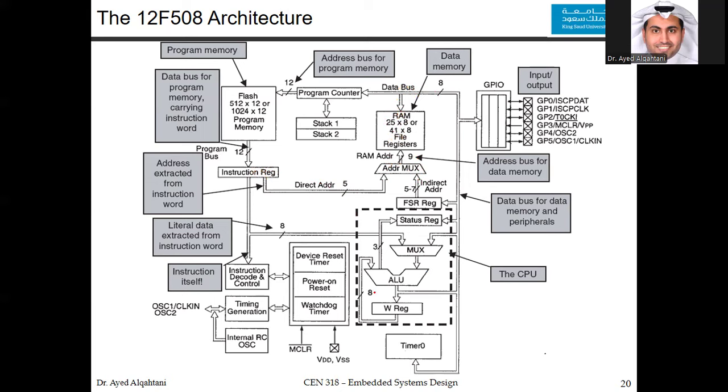And you can see here we have the CPU or the ALU, where you have either an immediate value or the variables that you get from the memory right here. And you have a multiplexer to choose which one you want to use right now. And then you execute using this ALU. And you can see that the result of the ALU could be fed back again to the ALU for an incrementing calculation.